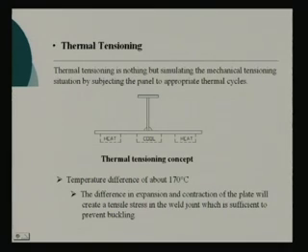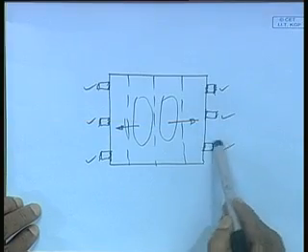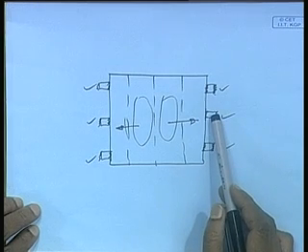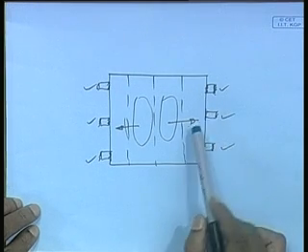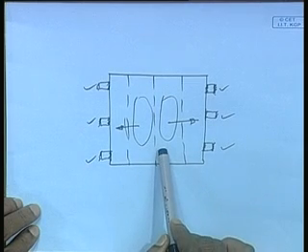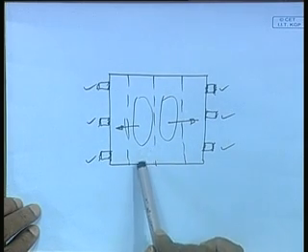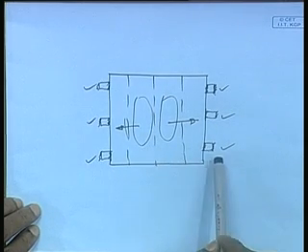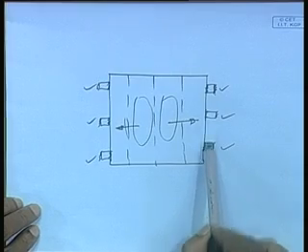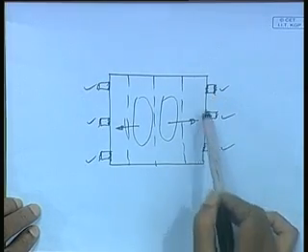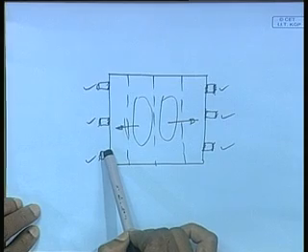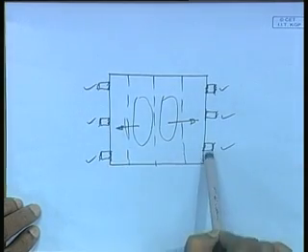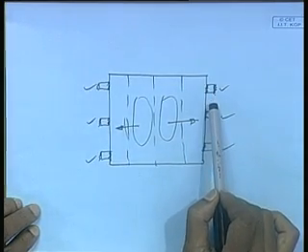And then we talked about a tensioning method by clamping the plates in such a fashion that the plate comes under tension. When the welding is being done, the plate is already in tension. How is that achieved? That is achieved by suitably welding the clamp, how the clamping is being done, just by welding lugs. So, on one side the lugs are welded, on the other side lugs are welded.